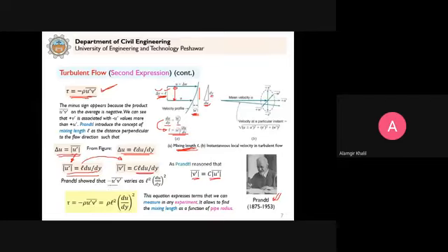And this quantity here can be written as L into du by dy and L into du by dy, and this c we bring into this mixing length L. So that is why this component is now equal to L square into (du by dy) whole square.